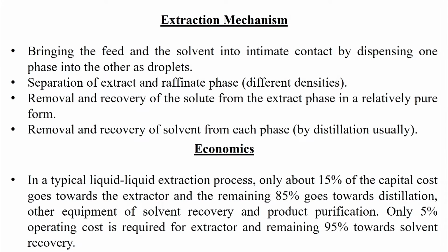Suppose in the beginning we have the feed with the solute and the carrier solvent, and then we add the extracting solvent into this feed and mix properly, so that it is dispersed as droplets.